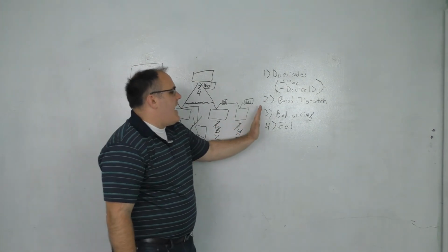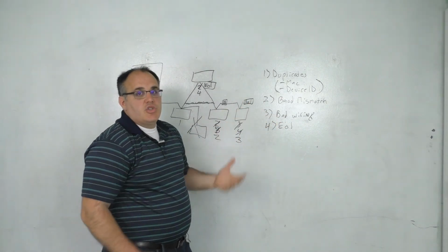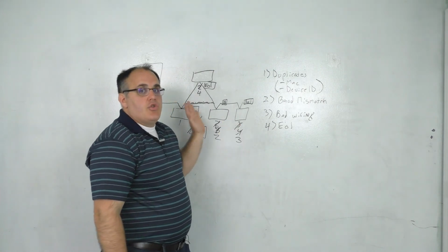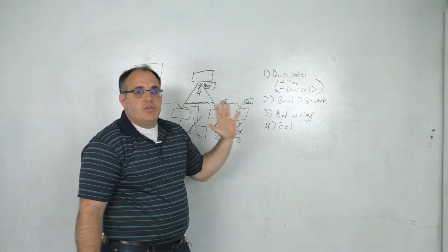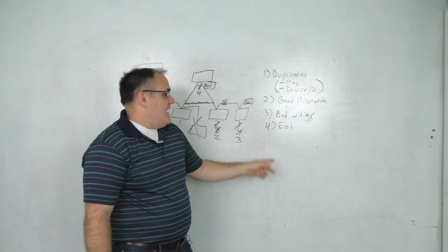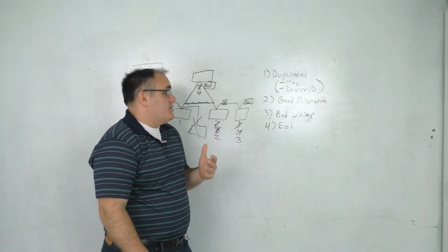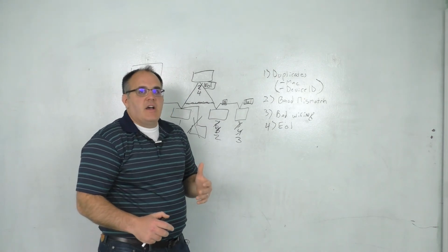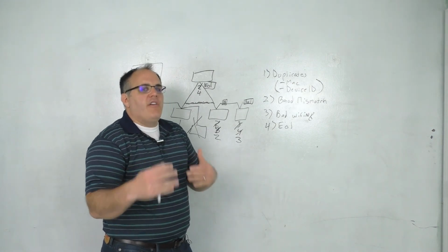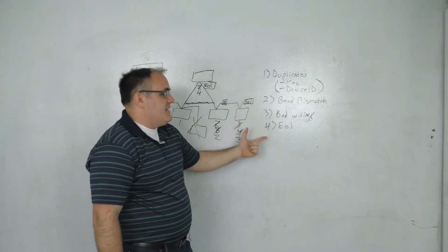So signs of bad wiring are very similar to baud rate mismatch, kind of flapping trunks, trunks that are slower, data that is slow. End of line is where you've got good communication to controllers up to a certain point, and then after that, the entire trunk's down. That's indicating an end-of-line issue. Now, all of these troubleshooting scenarios, I want to caution you, they're not 100% of the time. It's not always this. However, it is often this. More often than not, if you see the signs I mentioned, it's pointing to one of these issues.